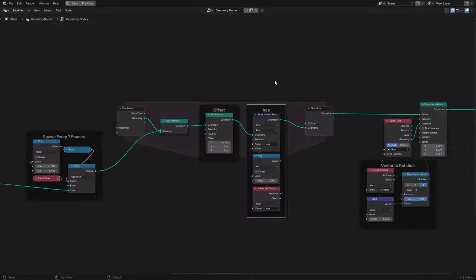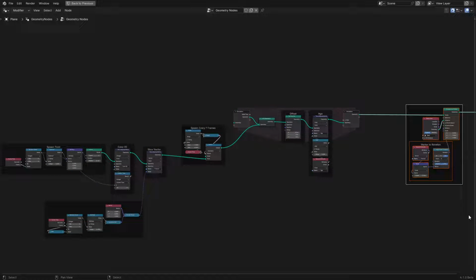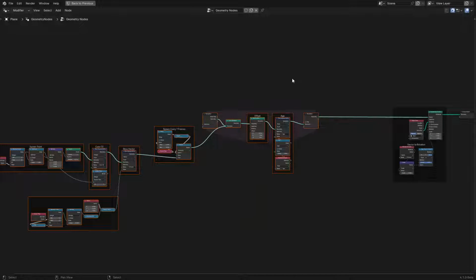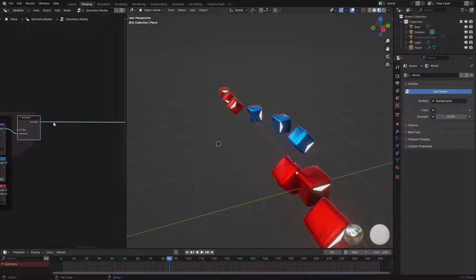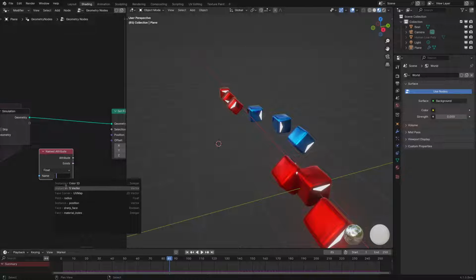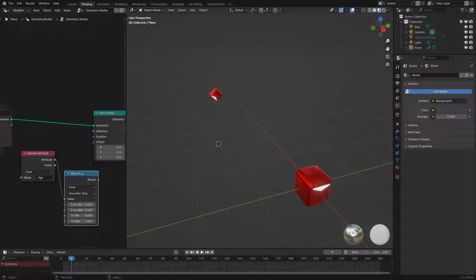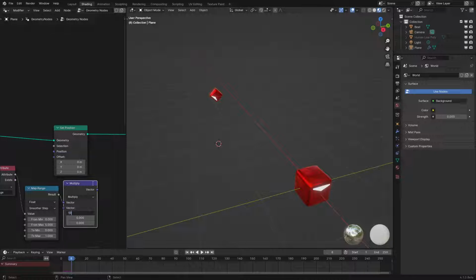Okay, age, there we go. So now for purely visuals, let's put that into there. When the age value is low, this is to make the illusion that they're scaling up. Well, actually, no, I don't need to do a scale up thing. This is purely visual after the simulation, but the age value is between a certain range. Let's reset the cache. Age, map range, and then multiply. So let's do 0, 5, and then we can multiply it on the x-axis by, like, 100.